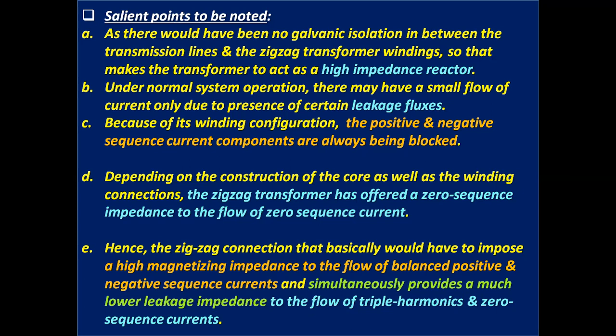D, depending on the construction of the core as well as the winding connections, the zigzag transformer offers a zero sequence impedance to the flow of zero sequence current.